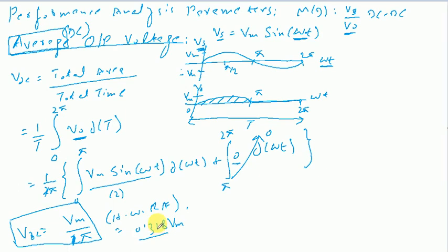Okay, so this is about the DC value of the output voltage. If you want to calculate the DC value of the output current, you can term it either IDC or I average, both are okay. That will be simply equal to the DC value of the output voltage that we have just evaluated divided by the value of load resistance. We can substitute the DC value of the output voltage, which will be equal to this factor.